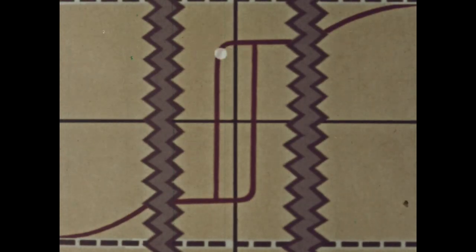On the other hand, wall motion in general is not reversible, and B lags behind H. The BH curve traces out the hysteresis loop whose area represents lost energy. There are several mechanisms that contribute to this hysteresis loss, two of which we will now discuss.